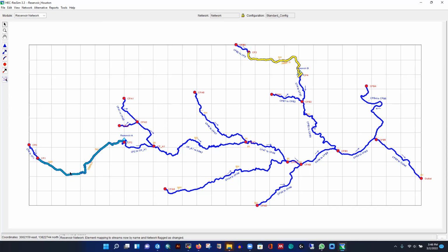How to calculate the capacity of a reservoir? You need to know the inflow to the reservoir and then the demand. If your inflow and the demand are different, the maximum difference between these two cumulative curves will give you the capacity of the reservoir. You have to calculate all this information beforehand, but for the time being, I'm just giving you the information and completing this model.